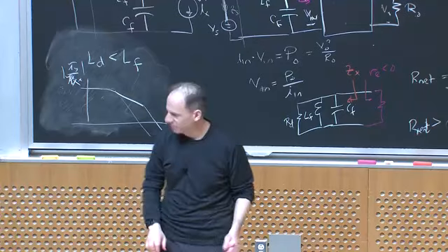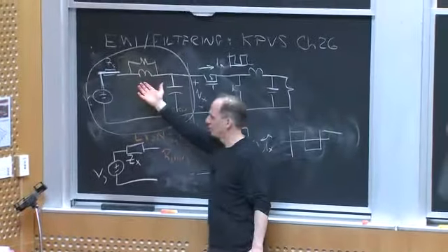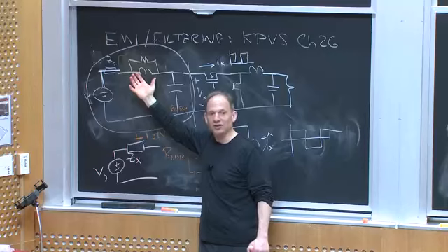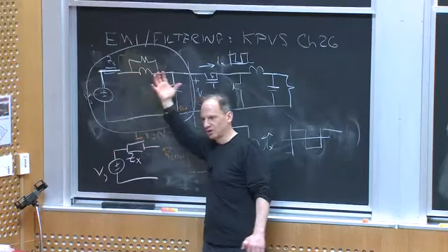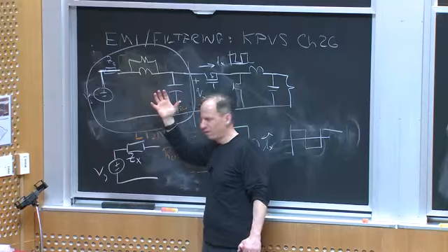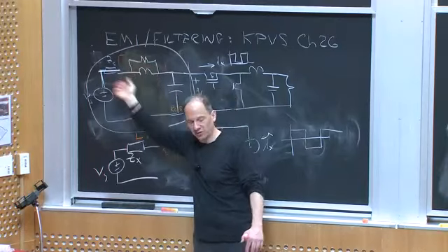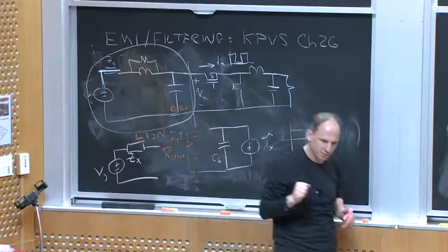The last thing I should have mentioned was, well, what if this LC filter isn't enough? You can cascade LC filter stages and get more and more attenuation. And again, there's rules for how you want to cascade those filter impedances. And again, those are in the handouts.